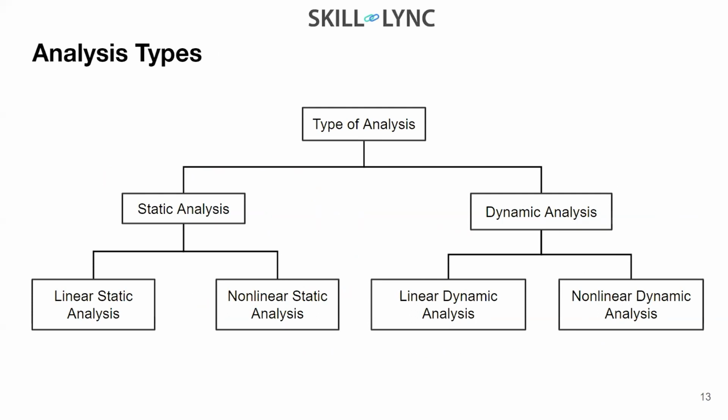Static and dynamic are actually the response of your structure with respect to the loads or the boundary conditions which you are applying. If that response is independent of time, then we call it a static analysis. If that response is dependent on time, then we call it a dynamic analysis. Okay, so that is one thing. Then within static and dynamic analysis, we have non-linear static and linear static analysis, and in dynamic, we have linear dynamic and non-linear dynamic analysis.